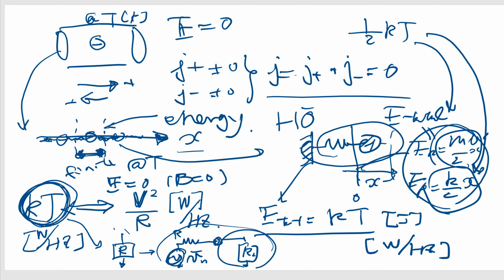In this simple model, if RL is the same value as the noise source resistance R, the maximum transfer of the energy power is achieved. This is the impedance matching case. The maximum transfer is achieved when RL equals R,